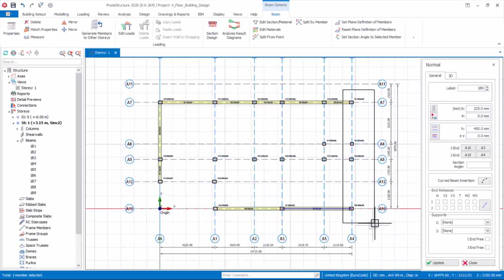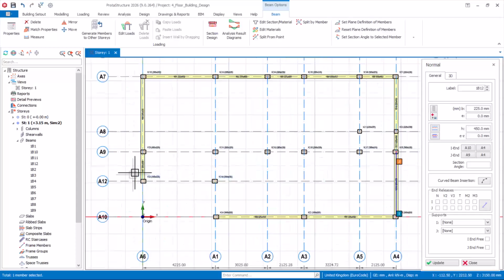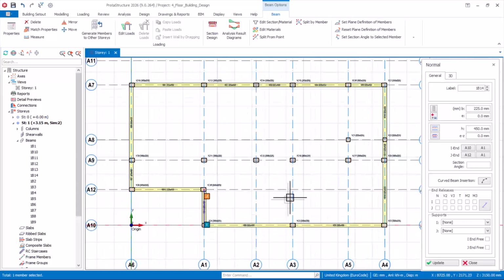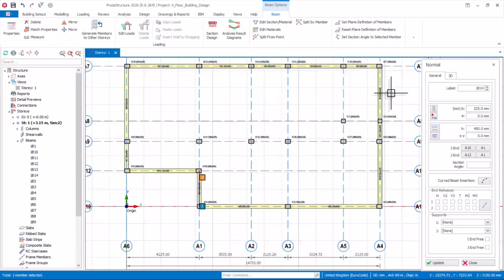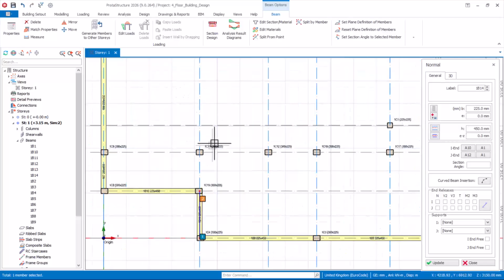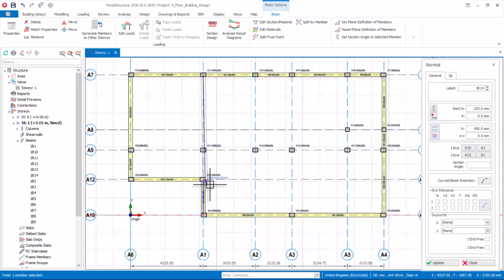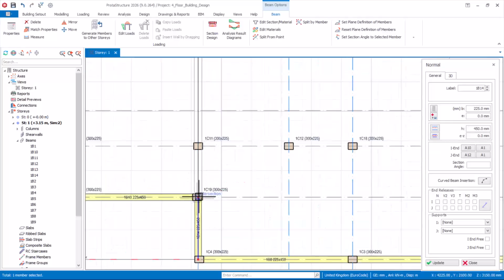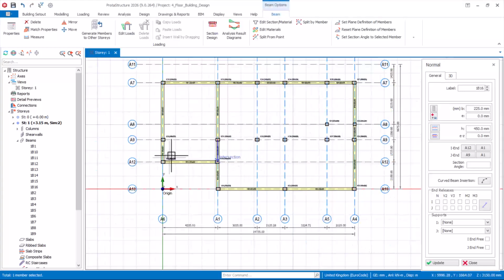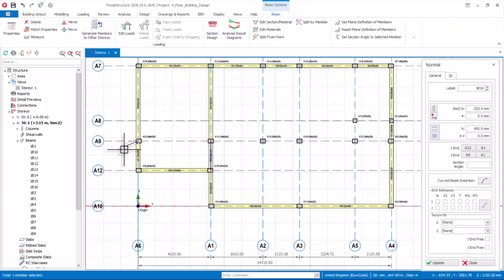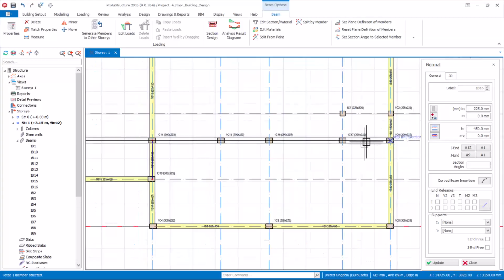So I'm actually placing the beam, inserting beam along the external wall. Okay, so after the insertion along the external wall, I will proceed to the internal partitions. Escape from the keyboard. I pick these columns and select it from here.